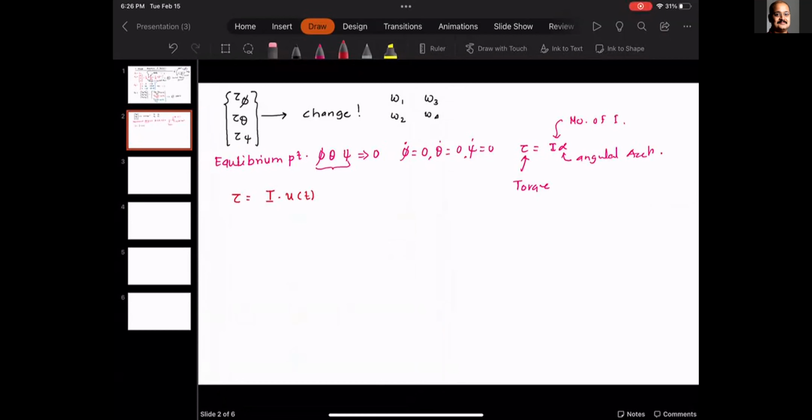So what does that mean? I'm arbitrarily going to say that my torque in the roll direction, torque in the theta direction, and torque in the psi direction are going to be minus Ixx multiplied by Kd multiplied by the error rate plus Kp multiplied by the integration from 0 to t of the angular velocity.